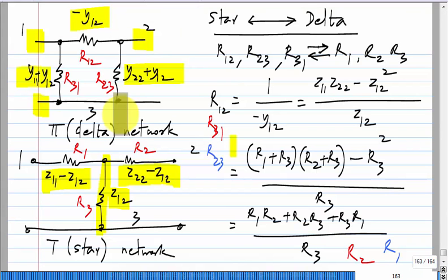We will have loads which may be, I mean, I think you have heard of 3-phase systems even if you don't know what it is. You will have 3-phase power transmission, right? So you will have loads connected like this between the lines or from the line to the star point and so on. And there are different loads. So if you have different loads, they are all connected in parallel. So the best thing is probably to convert everything to the delta form and then add up all the admittances. Okay. So that's why these transformations are useful.